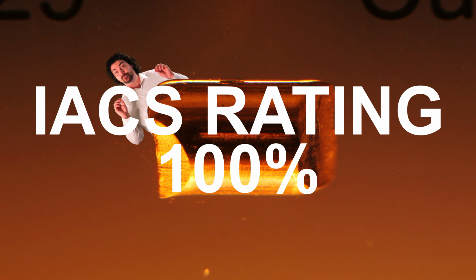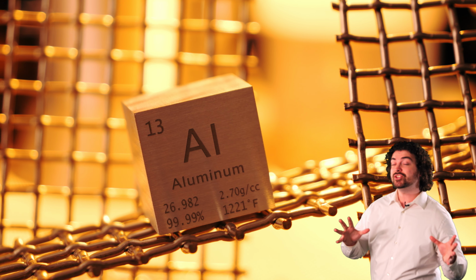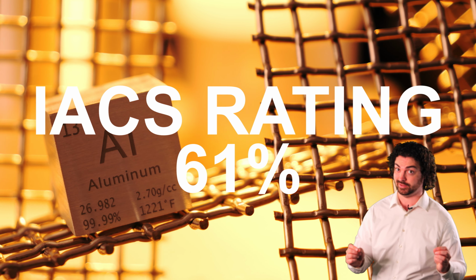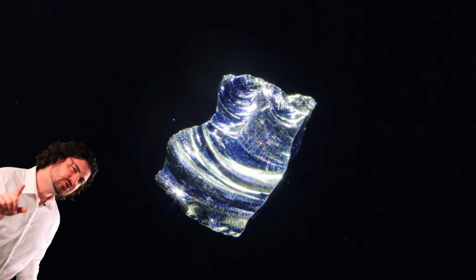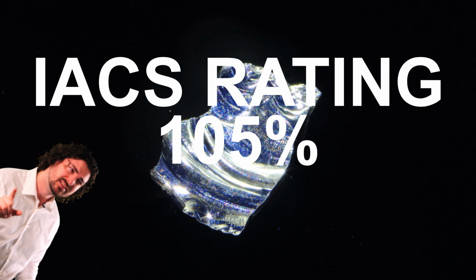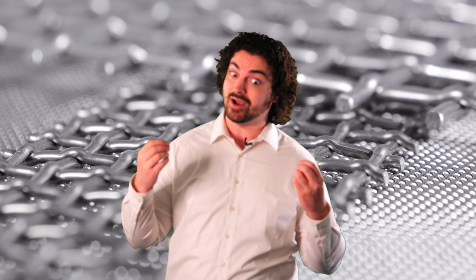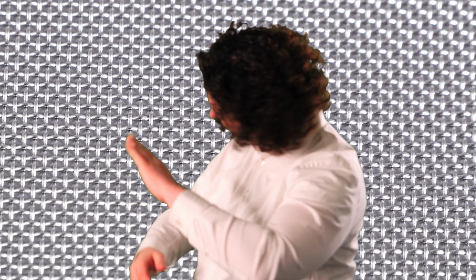Just to put into perspective, copper has an IACS rating of 100%. It's the literal benchmark for this kind of thing. Aluminum, which is also known to be very conductive, only has an IACS rating of 61%. The only element that surpasses copper is silver, with a strange rating of 105%. Let's not think about that too hard. Silver woven wire mesh is very rare because it is obviously very, very expensive.